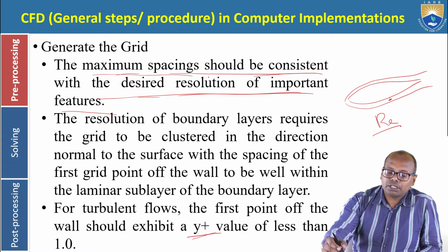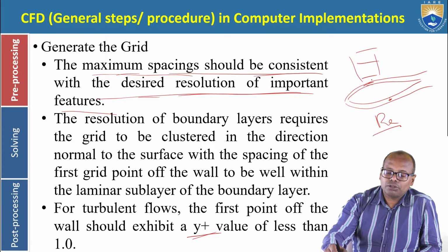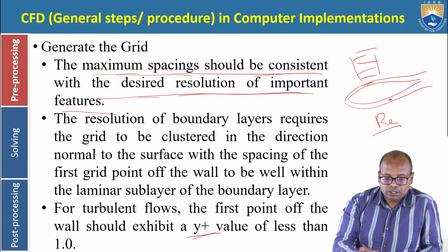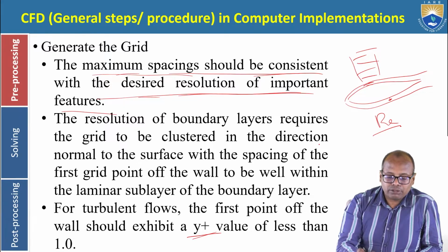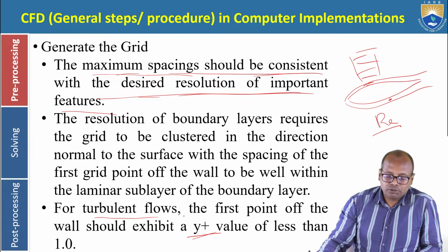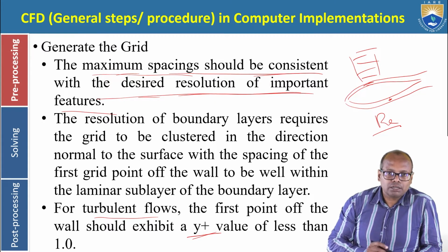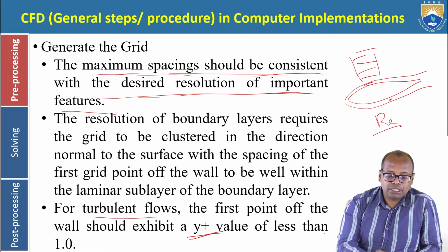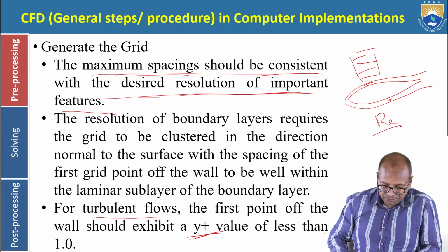Okay, so after that we can increase the space. Here with the small one, we are increasing the distance and making it bigger. So the resolution of the boundary layers is required, as I explained. Turbulent flows and laminar flows we can also consider. Generally most cases will be turbulent; very rarely will we see laminar flows. For turbulent flows, we have to ensure that y plus should be less than 1.0.